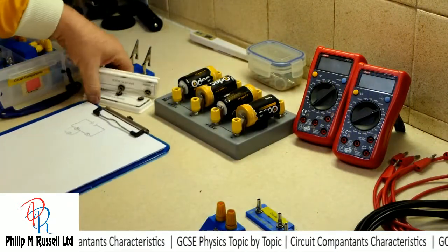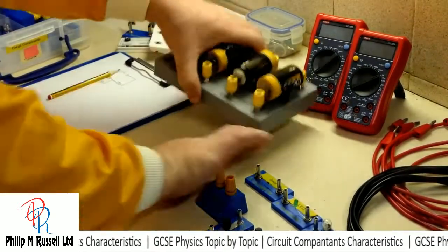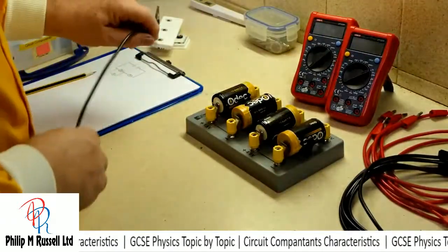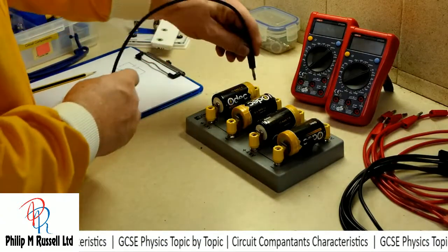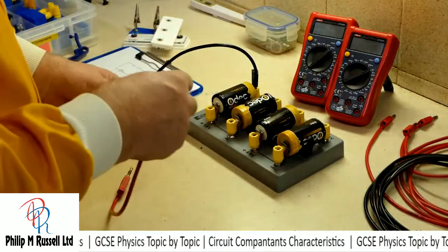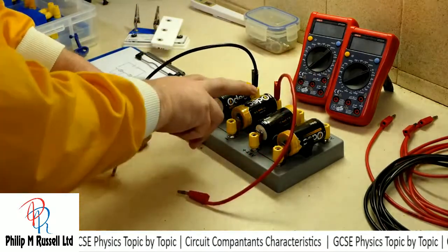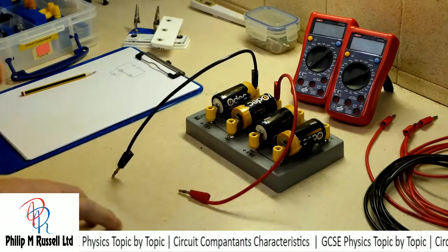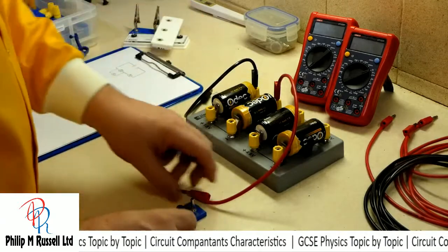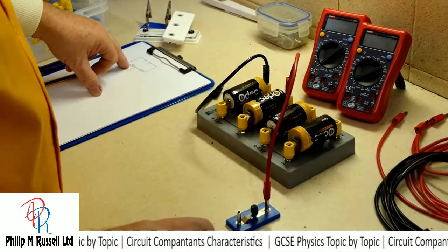I've brought my circuit over here because I want it for my basic plan, and let's see what we can do. I've got my battery. We're going to come out of my battery, and I can determine whether I want to do positive or negative. So we're going to do negative there, and let's just put a positive out of there. That's going to give me 3 volts, and my battery is then going to go to my switch. We'll take the positive side and go to the switch. From the switch I'm going to go to a light bulb.